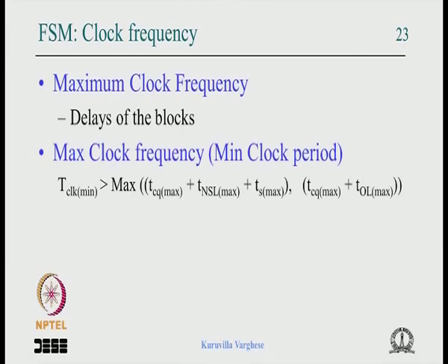In the tool when you simulate you have the opportunity to choose the fastest or the slowest delay. Corner cases can be chosen when you do timing simulation.